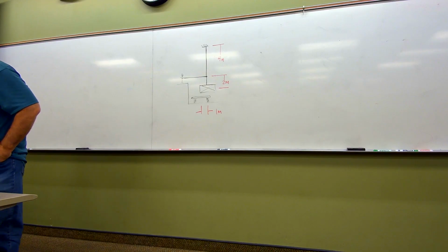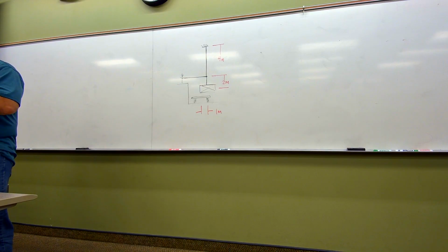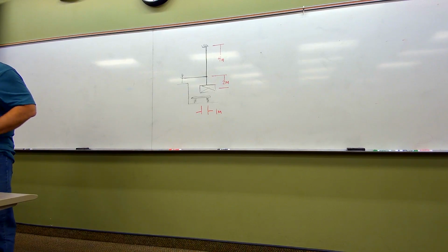And then we're told that it's a 50-kilogram crate. And folks, I think I've said this before, when you're working these problems, even before you start thinking anything, if you see something in the narrative that's not a standard unit, like in this case 50 kilograms, that's not a force, that's not a weight, that's a mass, right? Before you even start thinking about working that problem, fix that. Get that little bit out of the way so we don't have to deal with it.